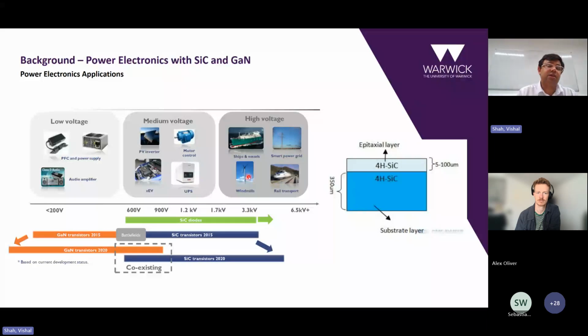It's green energy, renewables. And the important thing to note is that in 2022, there was thought to be a very clear delineation of where gallium nitride as a mature semiconductor and silicon carbide, both as power semiconductors, had their roles. And it was this field here, the 600 to 900 volt, where both material types could find a niche alongside silicon, actually. But what I should mention is that with the recent developments happening in both fields, I would say that gallium nitride is creeping up in voltage and silicon carbide might be creeping down in voltage as well. So the range of applicability is there.